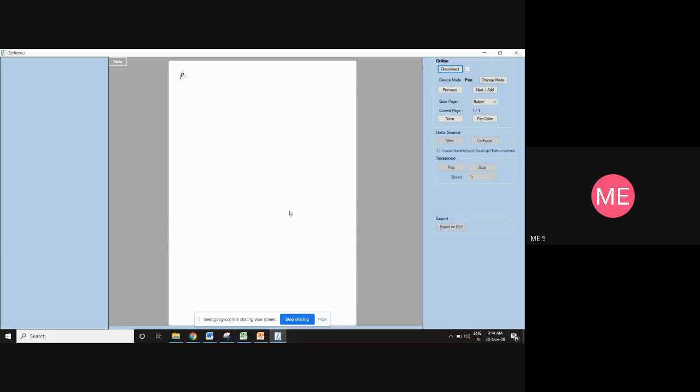We know P is equal to rho Q g H times efficiency divided by 1000. This is in terms of kilowatts. So he has given Ns is equal to 240 root of N by m, and Ns is equal to 206 root of N by m. If I use P in kilowatts, I'll get this; if I use P in HP, I'll get this.